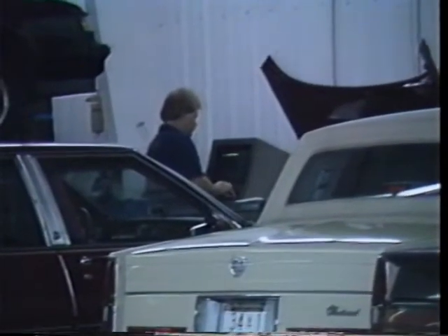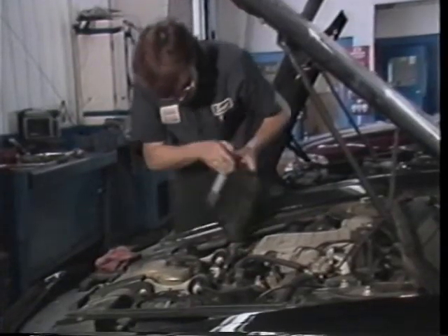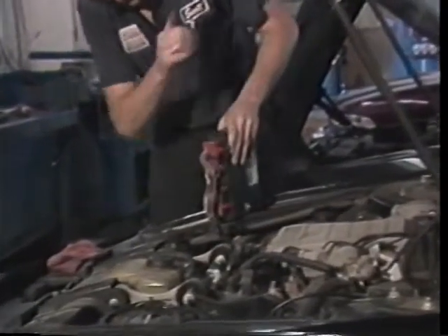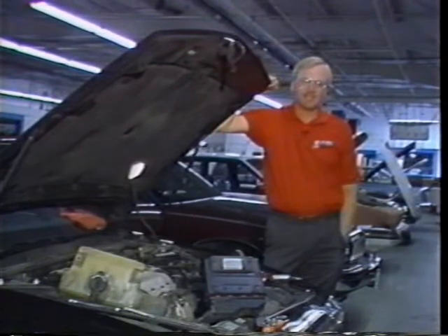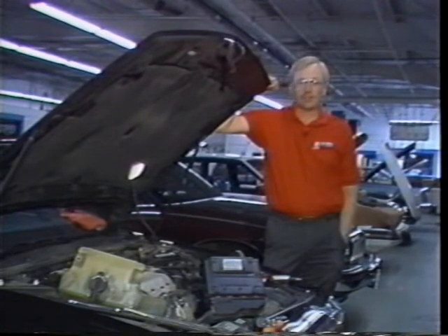But even if permanent damage is avoided, a short on any of the circuits will cause a disruption of normal ECM operation for the instant that the short occurs. This may cause the ECM to reset, creating the false impression that it is vibration sensitive or faulty. Reset is the ECM's normal way of coping with large voltage spikes. An ECM reset does not necessarily mean that the ECM is faulty or damaged, only that it is being subjected to abnormal conditions. So here's the correct way to avoid false readings and damage.